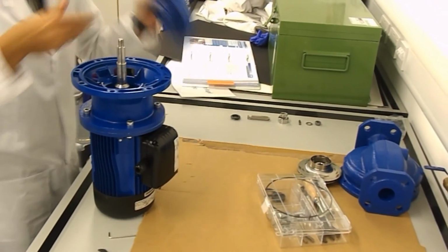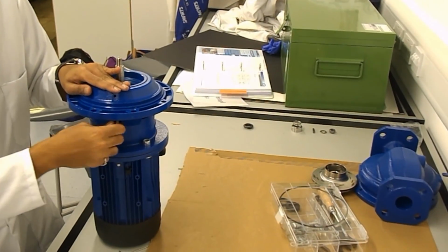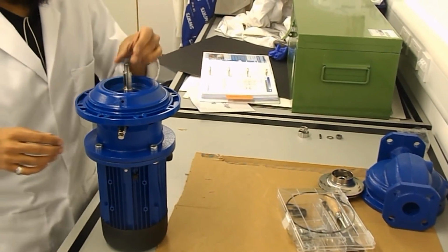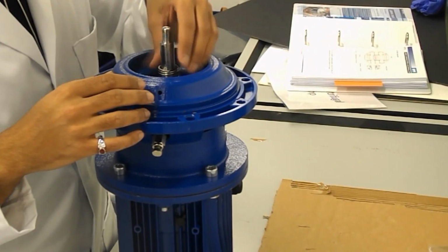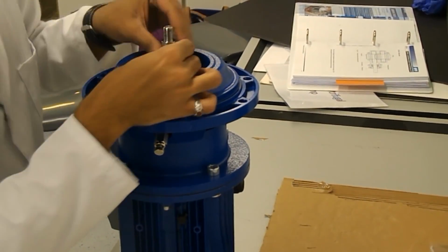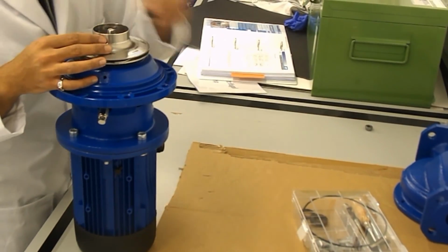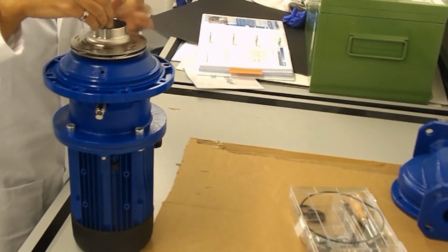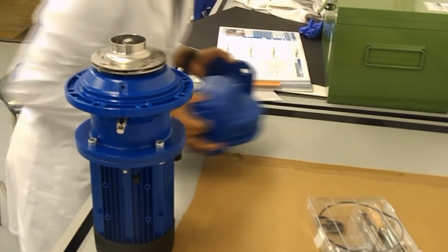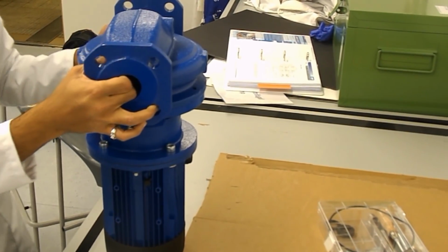The housing cover is then placed on top of the entire arrangement. The whole arrangement is screwed on via a hexagonal head screw. The impeller is then placed on top of the housing cover and kept in place with the aid of washers and hexagonal nuts. Lastly, the pump housing with compensating ring and spacer ring is placed on top of the whole arrangement and tightened with screw nuts. The pump is now fully constructed.